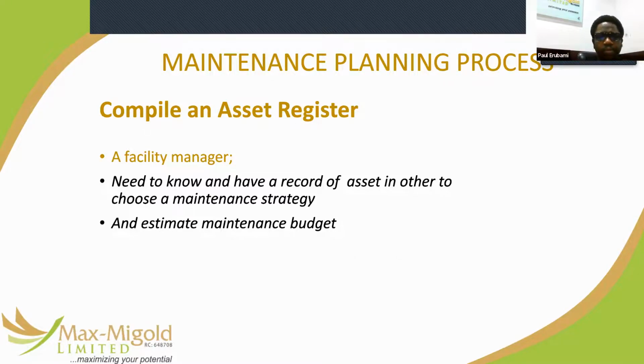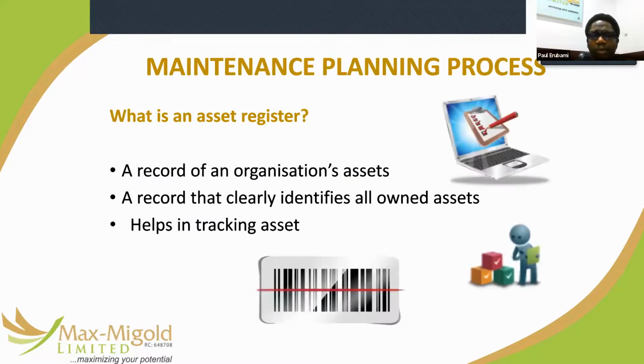All right. And because you have that list of assets, quantities, and all the other details, you can now create a maintenance budget, which is often an estimate, but you must use best judgment and experience from historical data to come up with it. So you should have a budget for both the reactive and the predictive, as well as the planned preventive. I mean, that's the preventive, predictive, and the run-to-failure items.